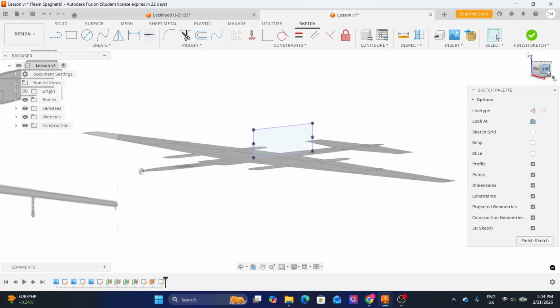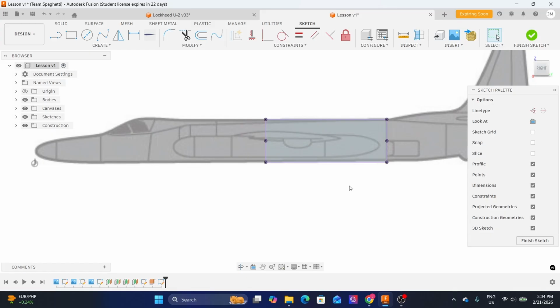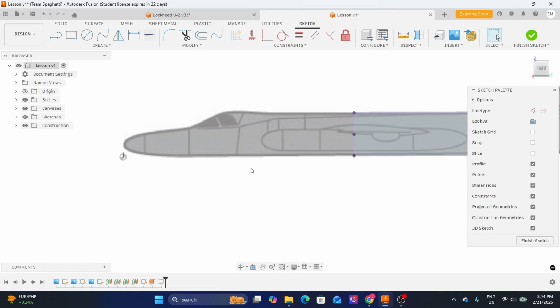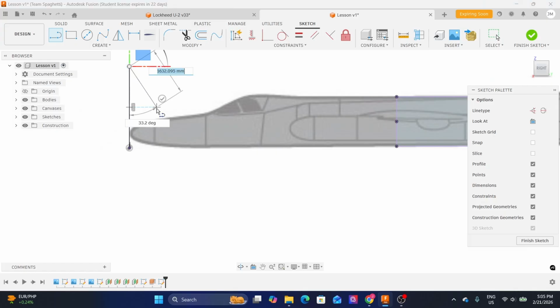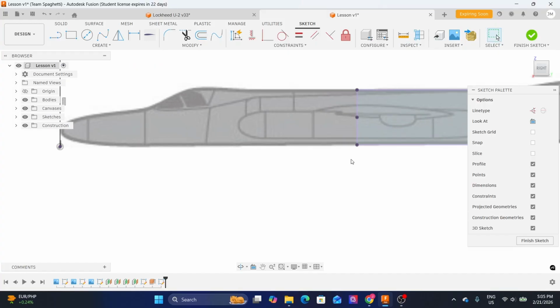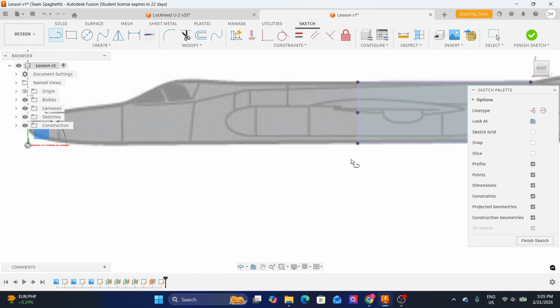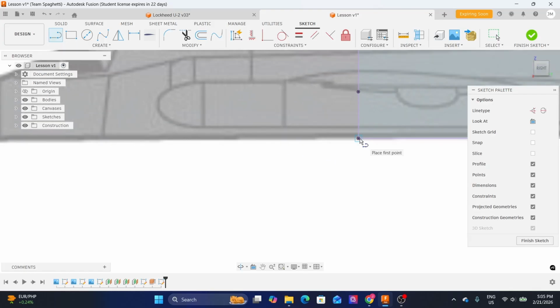So let me go ahead at the right side view. Okay, that is okay for me. And then I'll create construction lines first. So line here from the origin point. So select it here, first point, and then second point here. And then hit check, this button right here, once we're done. And then again another line. So L on my keyboard, or here, you could select it, and then snap it at this first point.